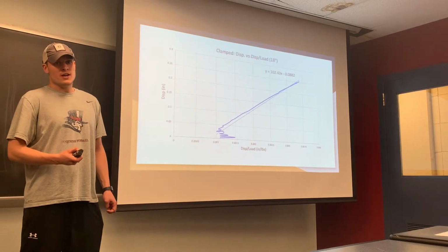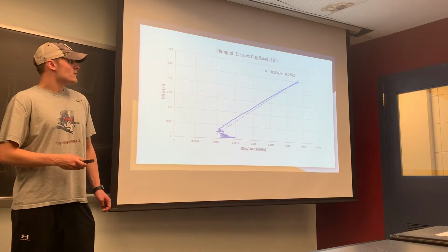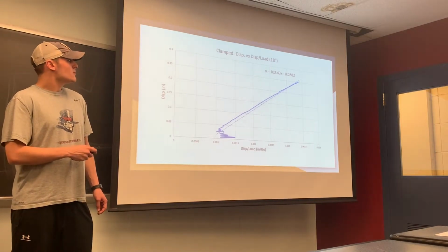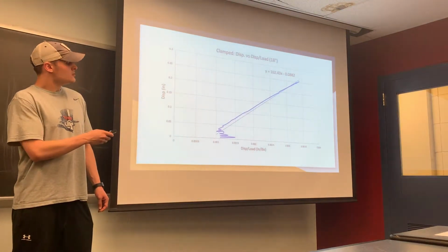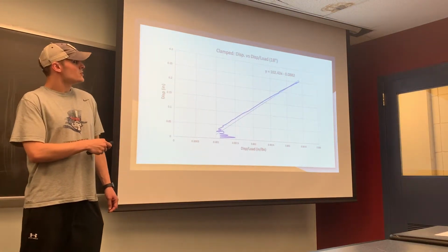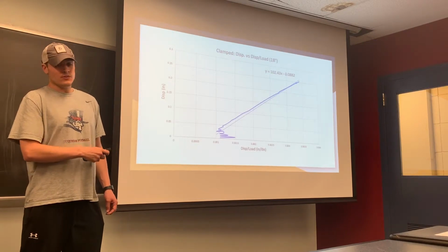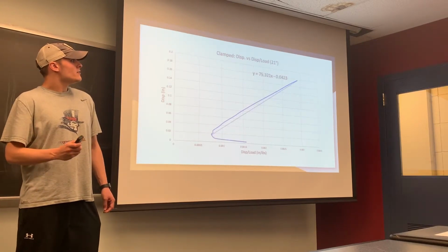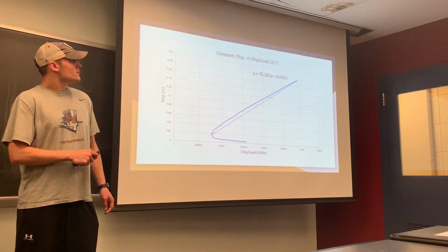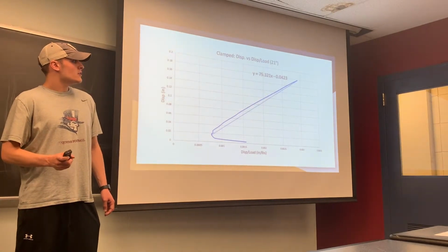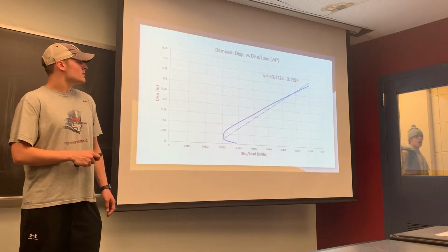So to evaluate our data in a different way, we also graphed displacement versus displacement over load. After applying a line of best fit, the slope of that line should be our P critical value. So as you can see in this one, for the 18-inch length, our slope at 102 is the P critical value here. And then increasing the length of the columns, it'll decrease for the 21 inches. And for 24 inches, just the same way as it did the last graph.